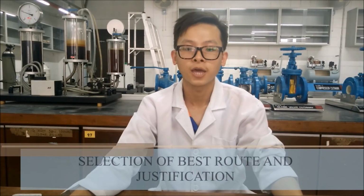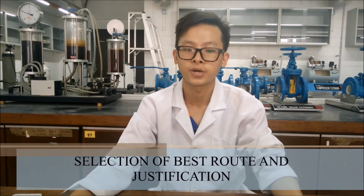Among the three commercial chemical reaction routes in the acetone production discussed above, the catalytic dehydrogenation of isopropanol is chosen for our plant. The cumene process is most common worldwide, but it generates too many byproducts, and this will lower the purity of the acetone produced and increase the production cost by separation because we need extra separation equipment.